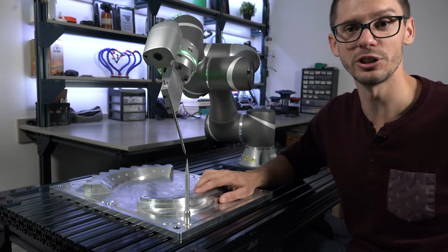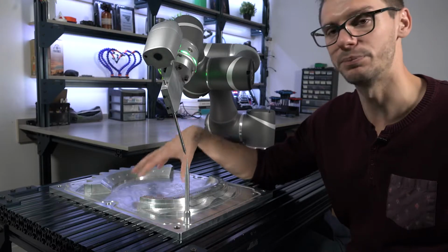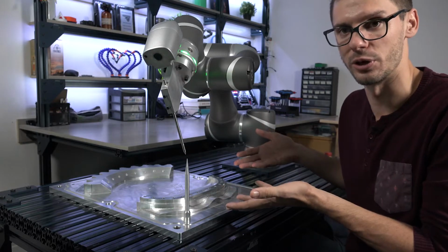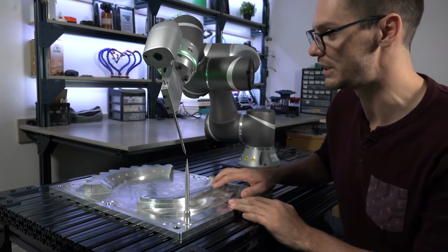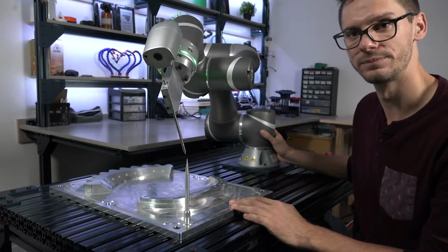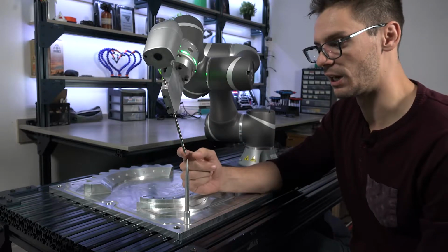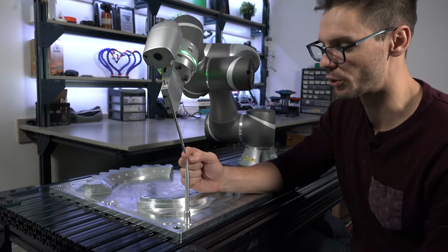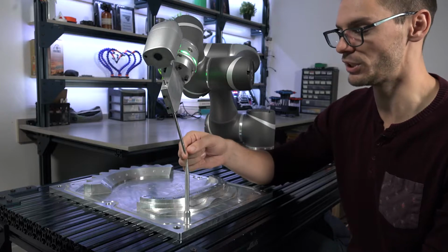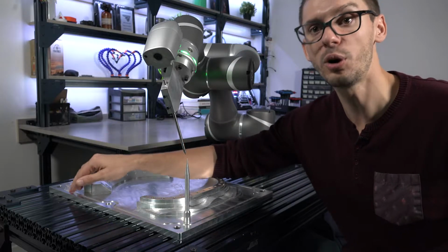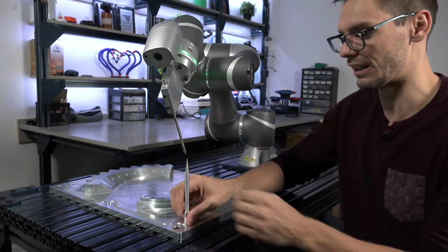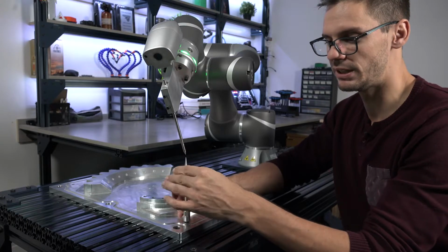In this tutorial, I'm going to show you how you can position this part in the virtual station so that it matches the actual position of the part in the real world. So in other words, I need to show RoboDK exactly where this part is with respect to the robot base we have here. Now that we defined our TCP, the tool center point XYZ with respect to the robot flange, we're able to use that position in that robot as kind of a probing tool to teach RoboDK this specific position. As for now, I don't need to have my TCP definition tool.